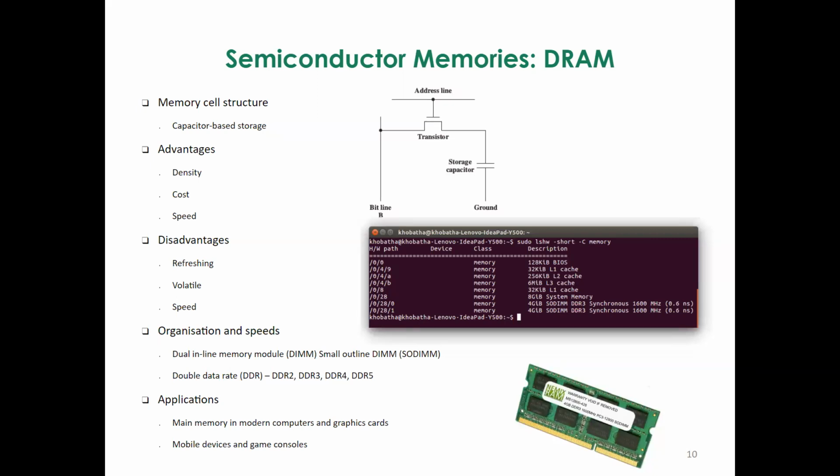So what happens is that in terms of design, RAM cells now include extra circuitry for recharging, so that cell is constantly refreshed to make sure that it maintains the data that has been persisted to it. So that obviously adds more complexity, that adds more delay, that even affects the power profile of your memory solution.